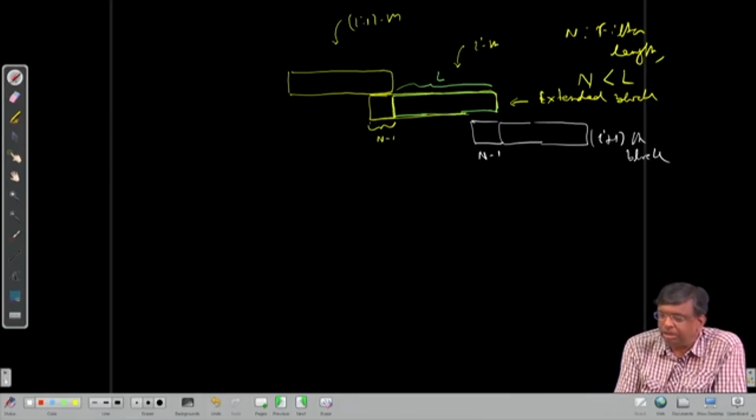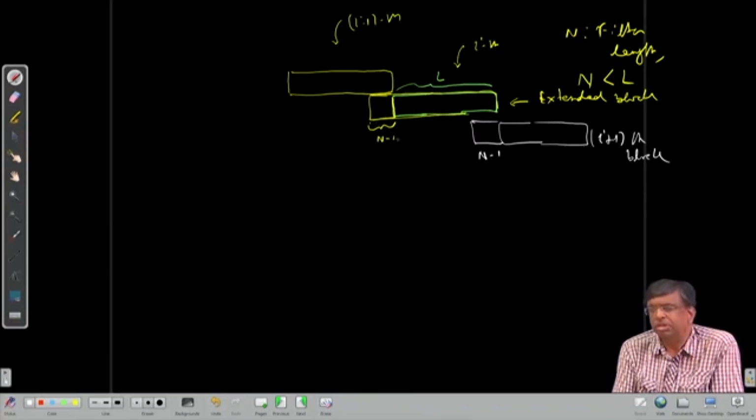So, we take each block separate, each extended block separately, carry out convolution with the corresponding filter impulse response vector or filter coefficient vector, which is fixed for that particular block, doesn't change, doesn't update. Carry out the convolution by overlap and save. That is, we discard the convolution output at these points, we take convolution output here, and this can be done efficiently using FFT.